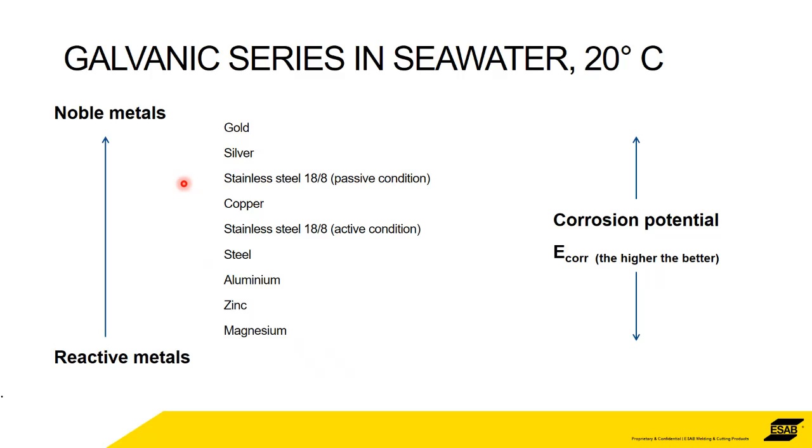And it's with an electrolyte in between, which can be water, seawater, whatever. It's the basis of how a battery works. A wet cell battery is exactly this kind of process. Once the reaction has started to happen, then the more reactive metal will start to corrode even quicker, and the more noble one will corrode less.